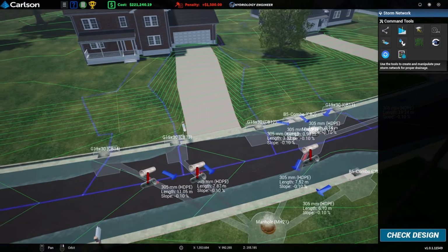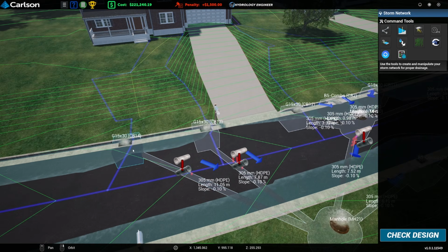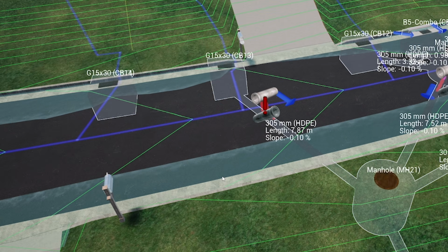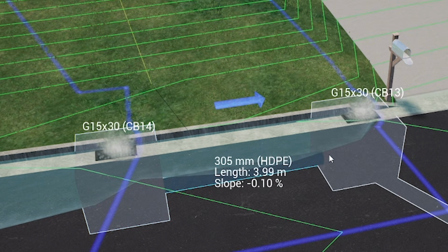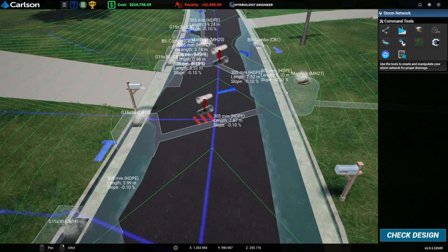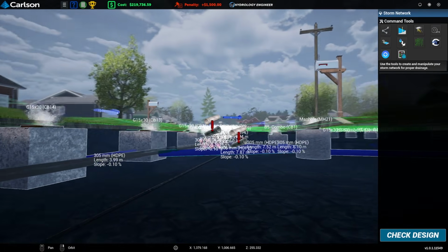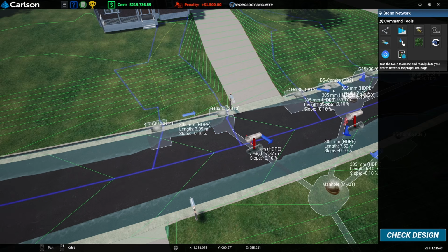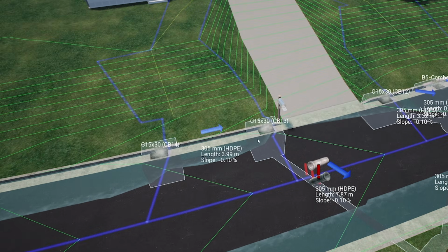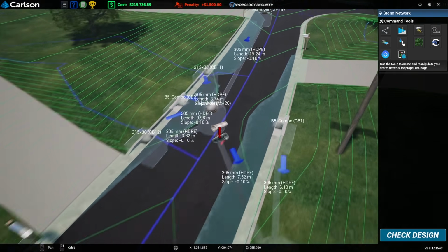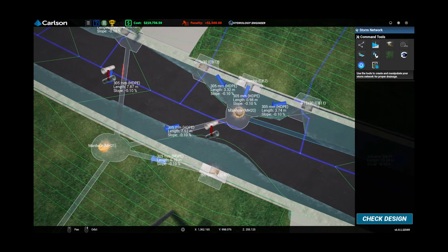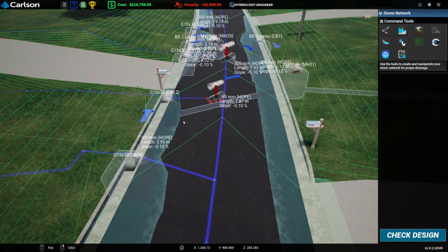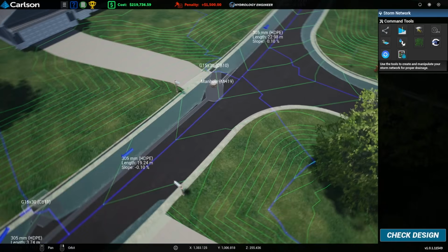In fact, something we'd probably do here is what we call a daisy chain. So rather than this gully going straight into this manhole, we'd probably delete that pipe there. Boosh. So the water that enters this gully goes along this pipe to that gully and then flows to that manhole. It means there's only one pipe we need to worry about clashing under there. And also remember, this is only there because the flow was sort of affecting downstream, wasn't it? So there's not actually that much area contributing to this one. So we're probably good to do that there. Worth noting though, this isn't best practice. Generally, daisy chaining is quite a lazy thing to do, but it does save you adding extra manholes occasionally. So some clients like it, some hate it.